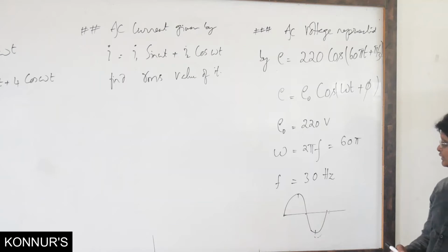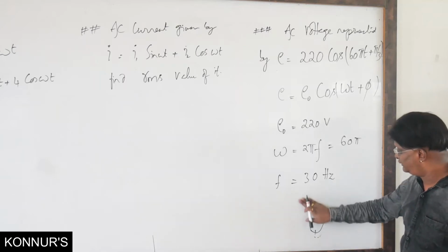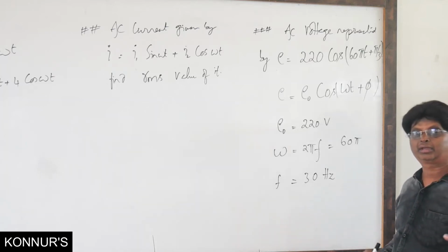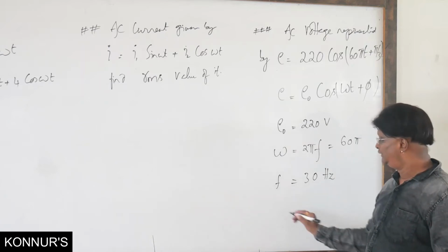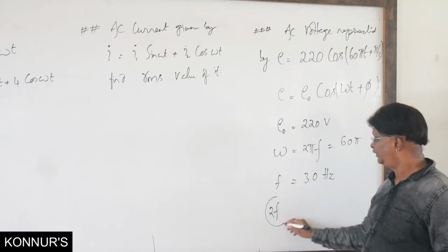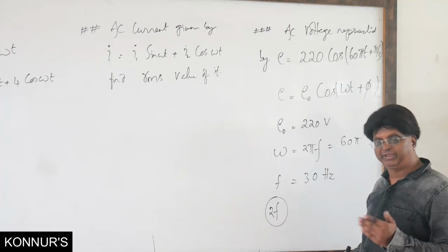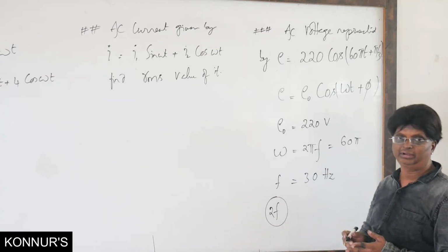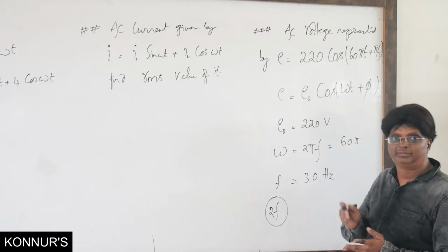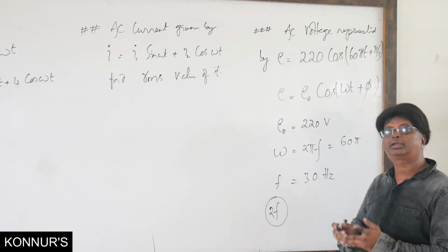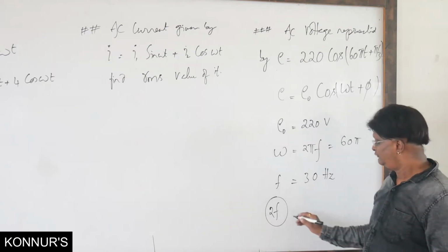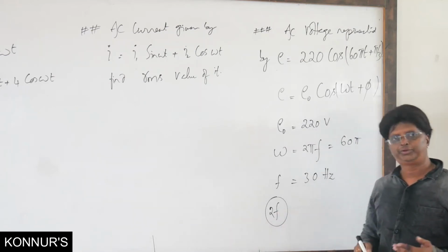And therefore, whenever instead of the frequency of the signal we are asked how many times current will be 0, the answer is 2f. So what is this 2f? 2f is the number of times for which current becomes 0 in 1 second, or current becomes maximum during 1 second, or current or EMF reversing in direction in 1 second. For all of them, the answer would be 2f.